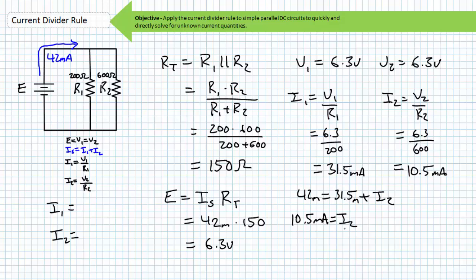Notice our smallest resistor, R1, had the largest current through it. Our largest resistor, R2, had the smallest current through it. And finally, the summation of all currents equaled the source current. I am reasonably confident we're correct. However, we can use any number of other methods to check our work. The most useful being that power in always equals power out. If you wish to verify the accuracy of our circuit analysis, by all means take the time and do so. This analysis yielded us correct results, and the techniques I employed should not have been surprising or new to you.